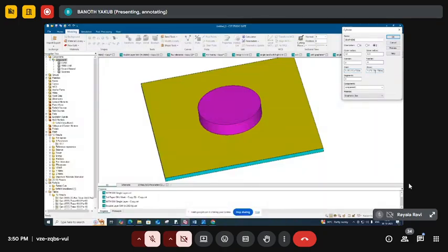Here you can give TGRA, the graphene thickness. So you can see clearly that graphene EPS and graphene metal are added. To collect the graphene EPS, click on preview. It will ask for the graphene thickness. The graphene thickness you can give as 0.2 micrometer. Just preview, and click OK.